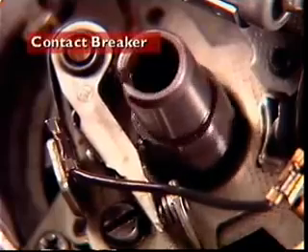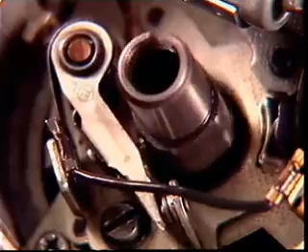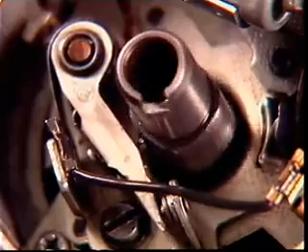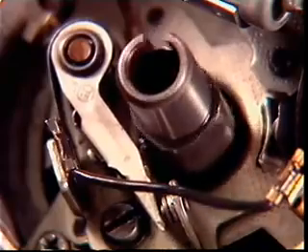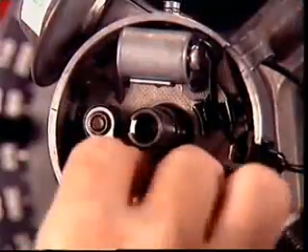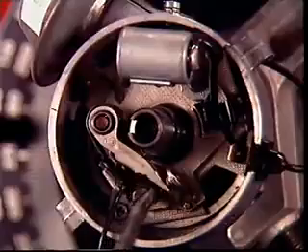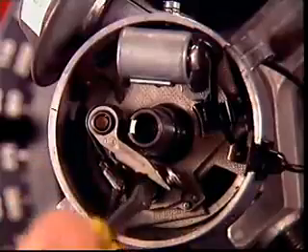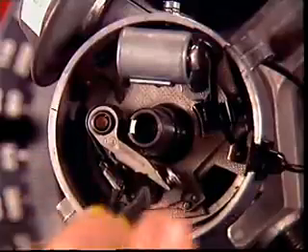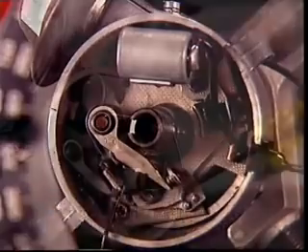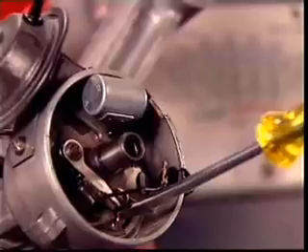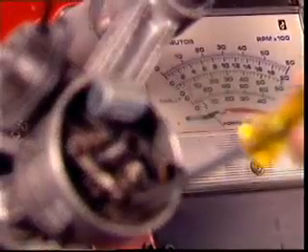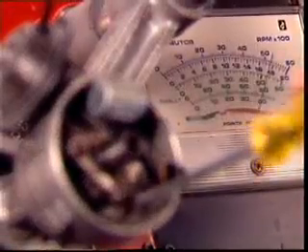The contact breaker is a mechanically operated electrical switch which is fixed to the distributor baseplate and opened and closed by the distributor cam with the rotation of the engine. The contacts normally form a self-contained unit fixed to the baseplate by a retaining screw engaged in a slot in the fixed contact. The slot allows for adjustment of the contact breaker gap and the setting of the dwell angle when fitting or servicing.